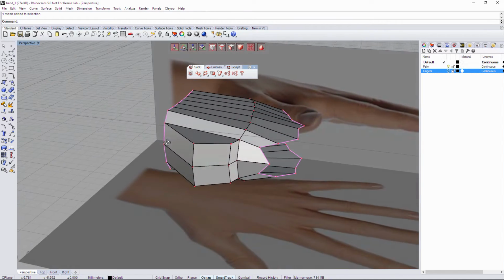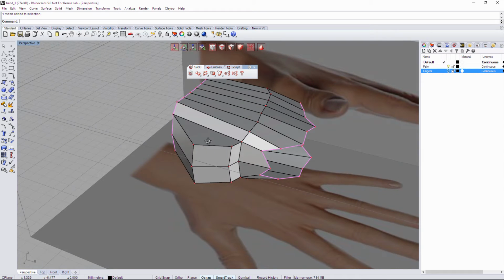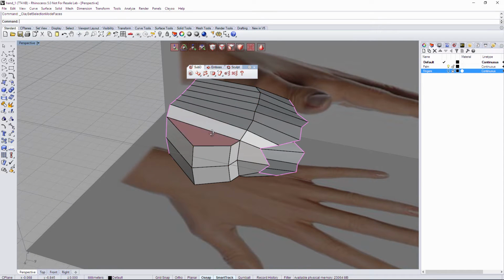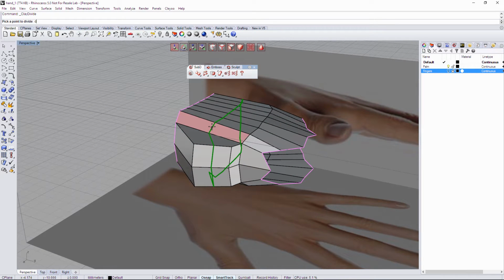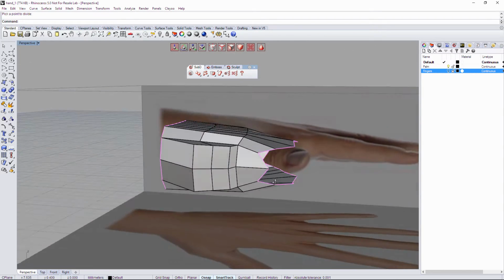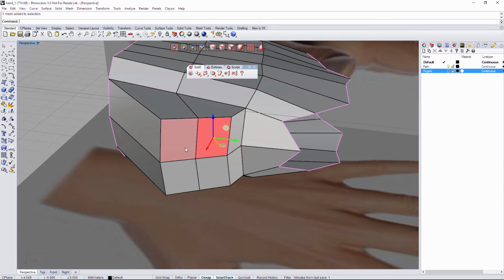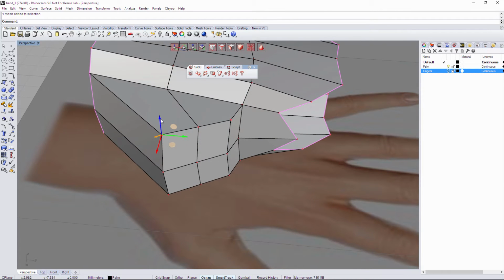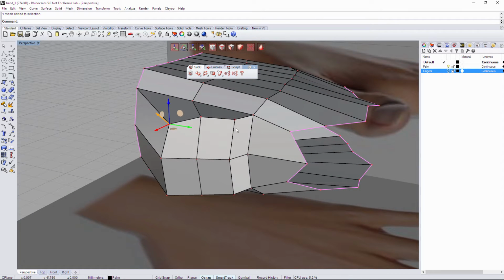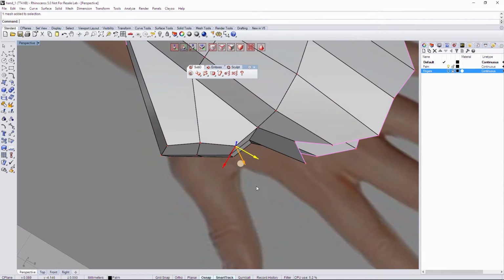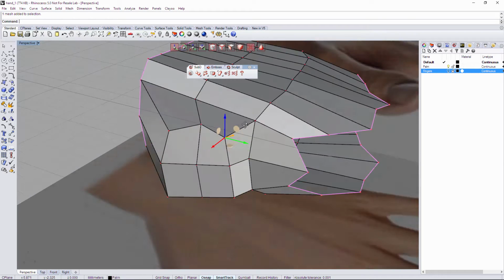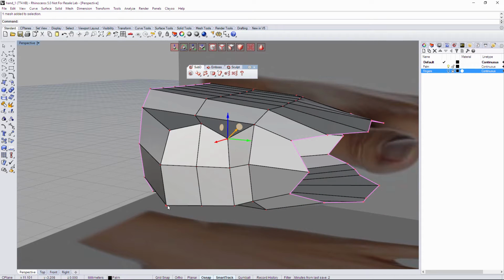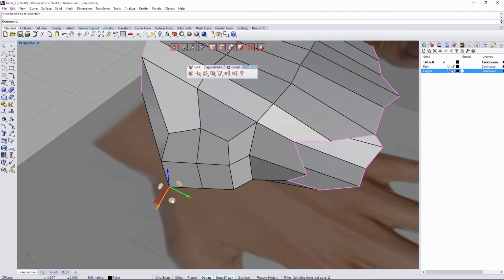So as you remember, we subdivide the object before creating the thumb. So what we have to do right now is just clicking D for divide when faces selection mode is active. Okay, and here we are recreating the subdivision. Okay, for our thumb, just to be the same style as our fingers. So just having this 8 edge shape in here.